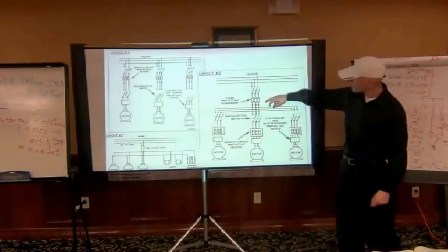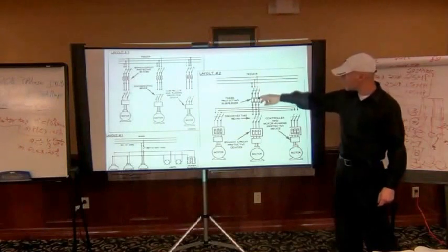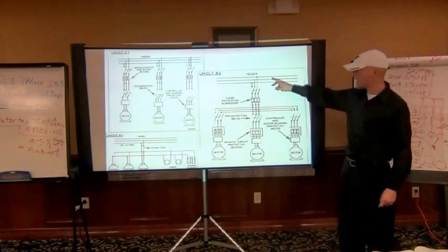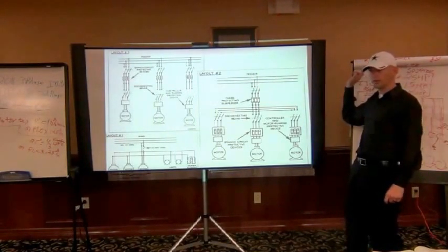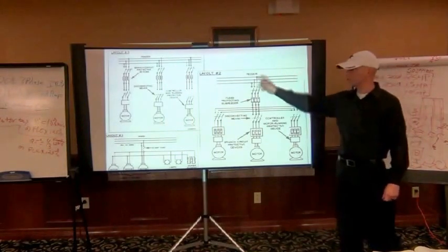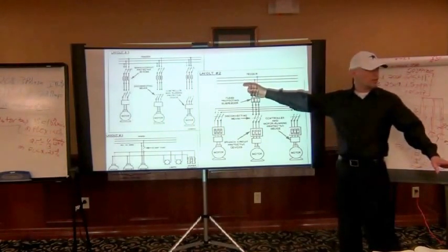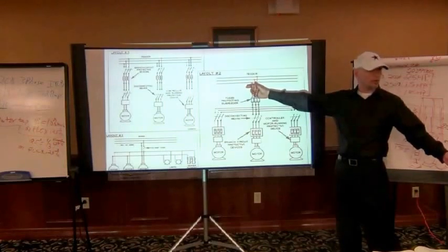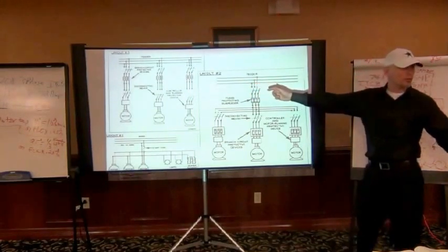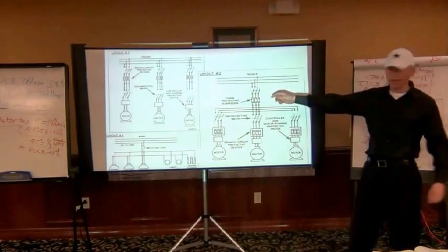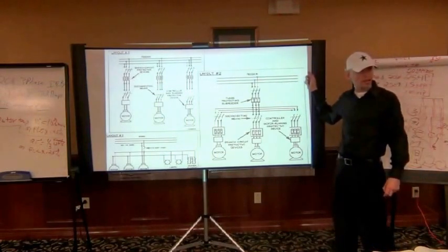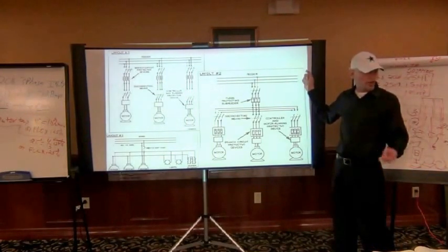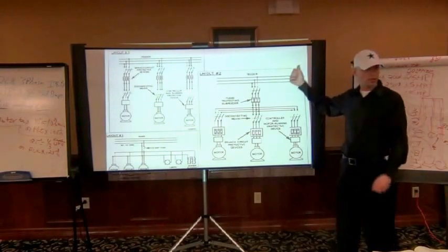And same thing here, if you had a fuse there, these two fuses would likely be the same size unless they have some other loads further down. If there's some other loads further down, then this feeder would have a different size based on what we did yesterday where you have the breakers, the receptacles and the outside lighting, that kind of thing. This feeder right here would be calculated all the way out with the sum of the non-continuous loads and any continuous duty loads that are further down there.